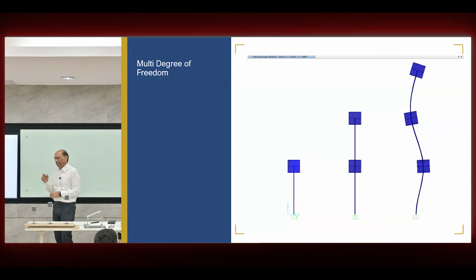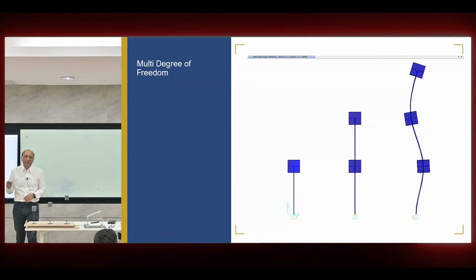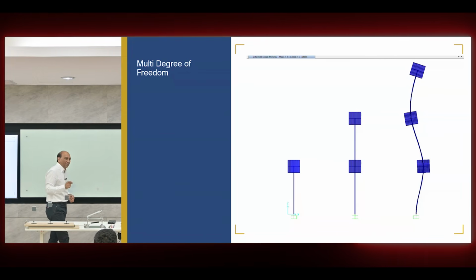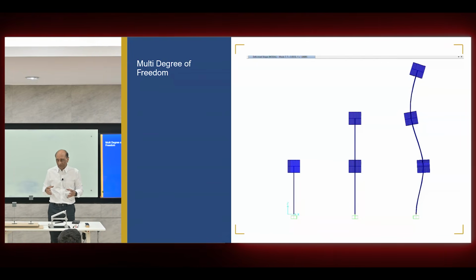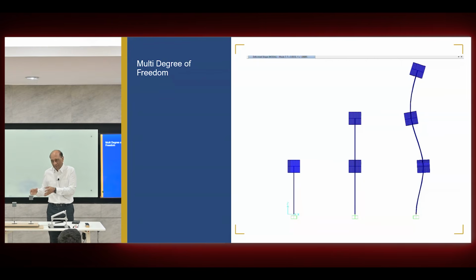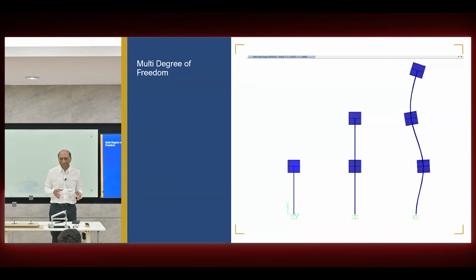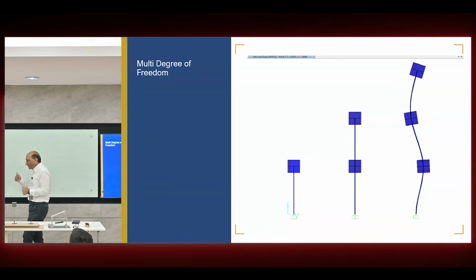So the first step in your project should be to find the mode shapes, frequencies, natural periods of your structure. Check if they are what you want and they are acceptable or not. And if not, fix it, bring it to what it should be. Three steps. All right. So now let's see what it should be and what it should not be.